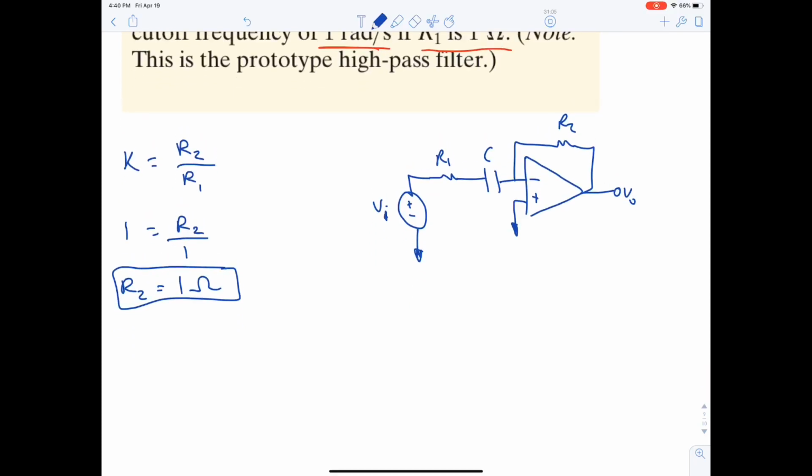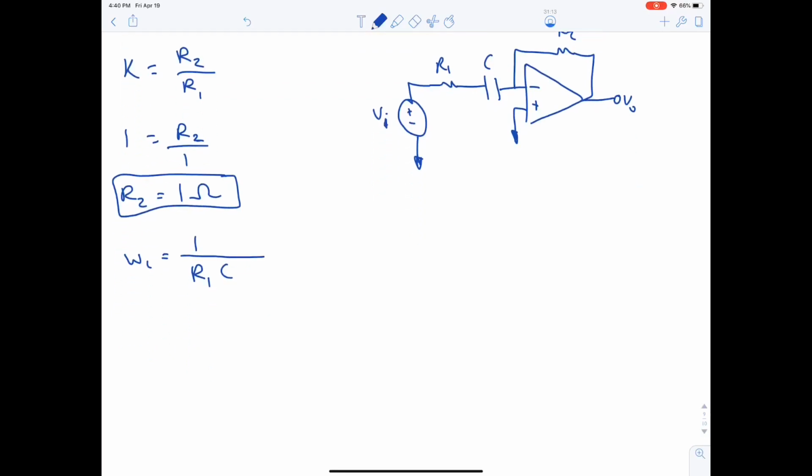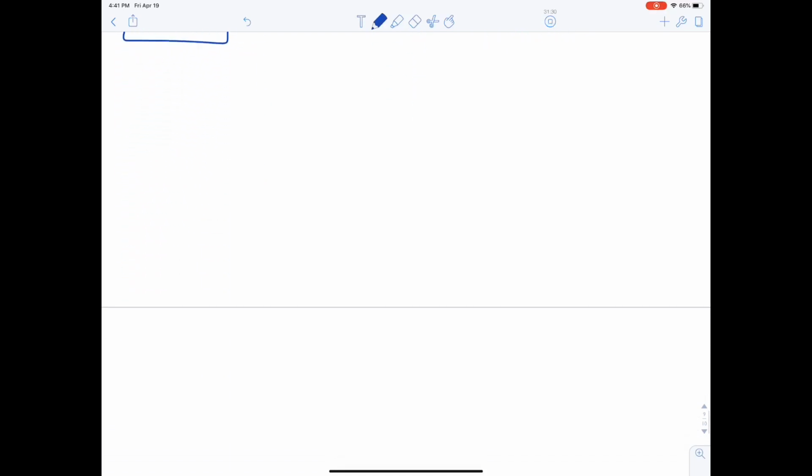Now, we need to find C through the omega C equation. R, C, which are R that is with the capacitor. So omega C is 1. And R, we just found it to be 1. Actually, it was given in the question. So C is 1 farad. This question is also simple. Now, let's take a more challenging question.